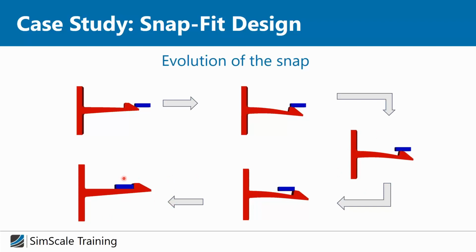Whenever we apply tangential load, or compression load, it makes no difference, it will keep both parts together until we release the snap fit, for example by bringing this blue part up again. Therefore it's a very smart way of joining two bodies, because it's actually adding pre-stress itself.